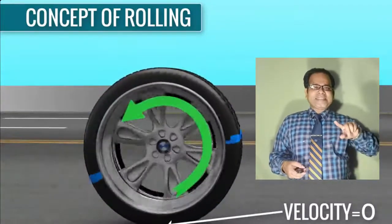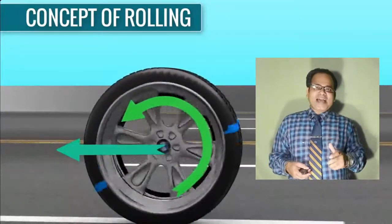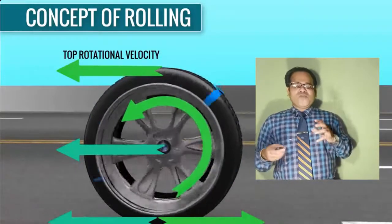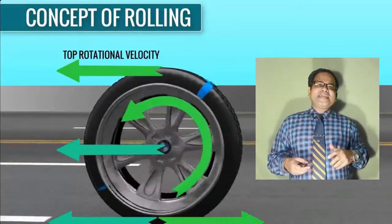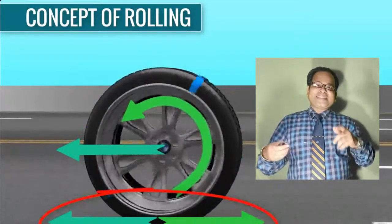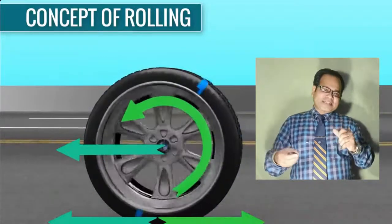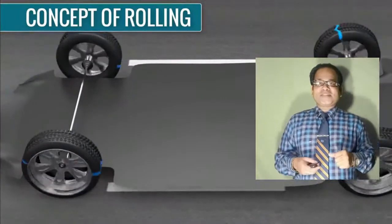The wheel rotates on its axis, while also moving ahead. So the wheel has two kinds of motion and two kinds of velocity as well. For a non-slip rolling condition, the vectorial sum of the translational and rotational velocity at the contact point should be zero. Just keep this simple concept in mind, and you'll be able to understand what ABS is and how it works.